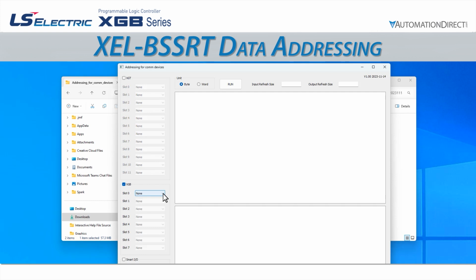we are using. As we discussed in our previous video on setup, we are going to have an XBF HD02A high-speed counter module, and that will be in slot 0. I can now add that in the software. We will also have an XBE DC32A discrete input module in slot 1, an XBE TN32A discrete output module in slot 2, an XBF AD04A analog input module in slot 3, and an XBF LD02S load cell input module in slot 4.